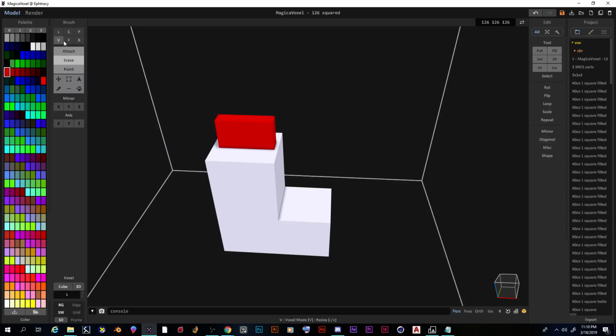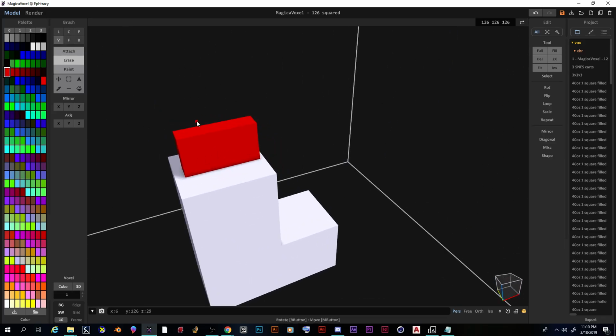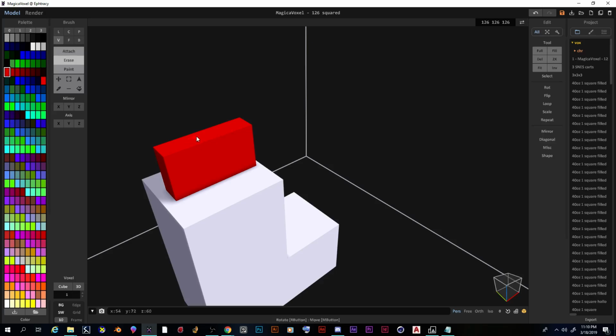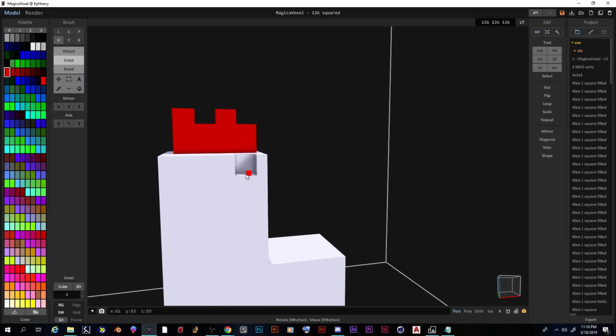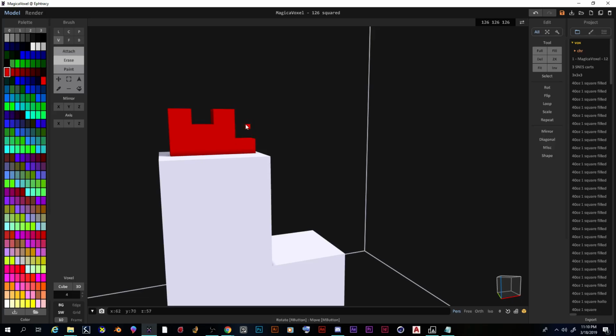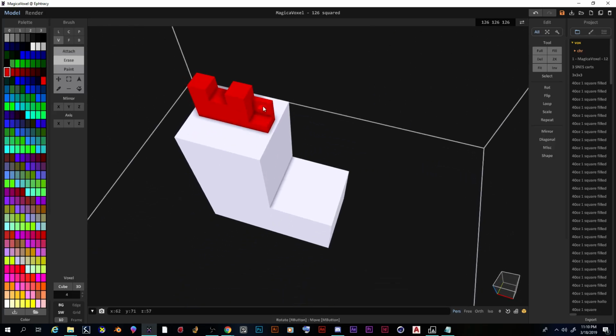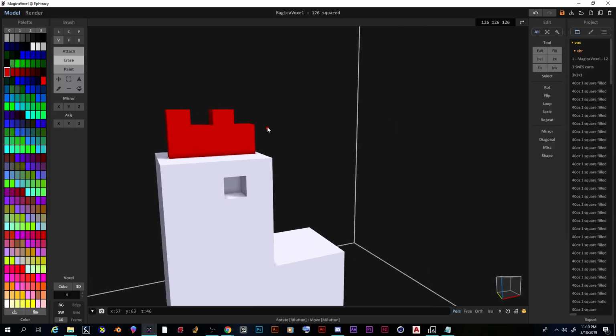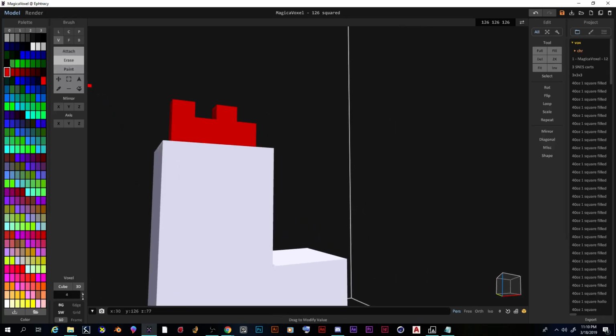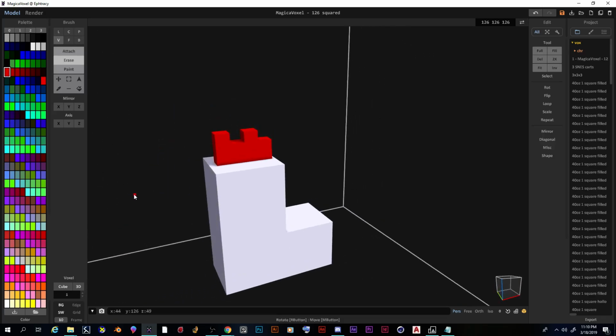I'm going to click on my voxel brush. This one we haven't used yet. Right now it's set for 1 voxel wide, and the voxel is just, you know, a 3D pixel. I'm going to set this for maybe 4. See the difference that makes? So I'm just going to vary that up a little bit. Okay, looks good enough. I'm going to bring that back down because I'm going to need that later.